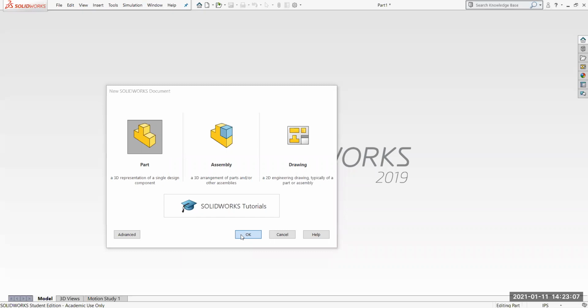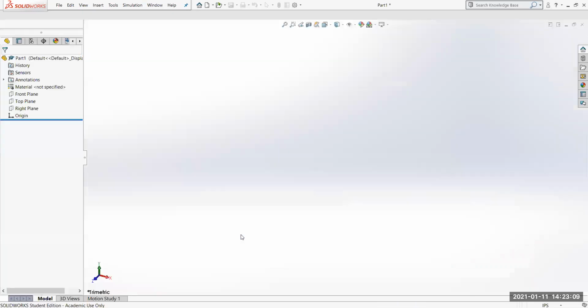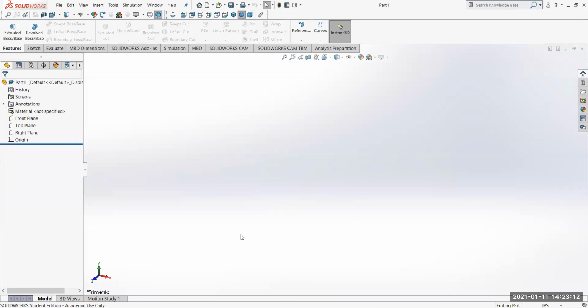There are several ways that we can start this drawing. It all depends on what you're more comfortable with. It's basically a base on this thing, and then the rounded portions on the top left side, and some cutouts on the right side. I think what I'm going to do is start with a 2-inch tall base and create the base first, and then we'll put the wings on the back side, and then we'll cut the holes in it. So I think that's the way that I'm going to start this thing.